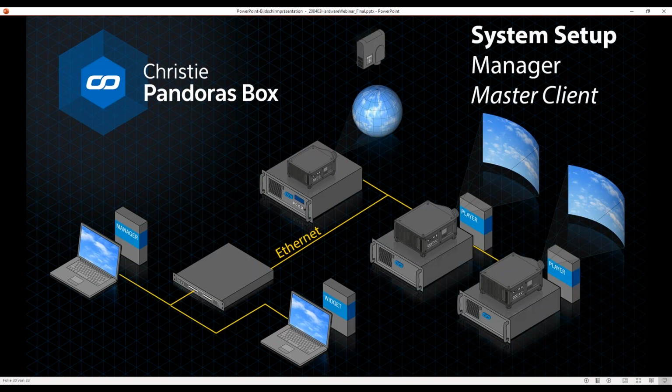And to take it a bit further, you can use the widget designer to control the manager, to control your GUI, to control your show. Same as before, everything is connected through a network. The manager goes into a network, the widgets go into your network, into 2 players and 1 server, and these are the output devices. So this is the typical way to set it up. If you have 1 Pandoras Box system, make it standalone. If you have 2 licenses, make a master and client connection. That's the most common way of doing it.